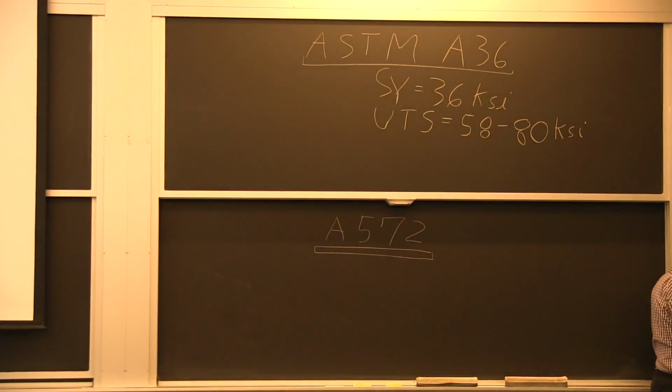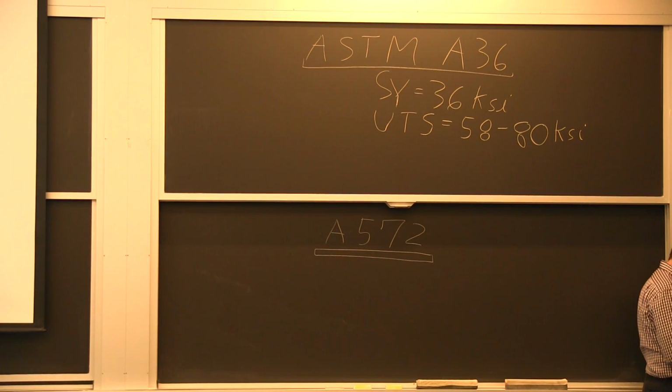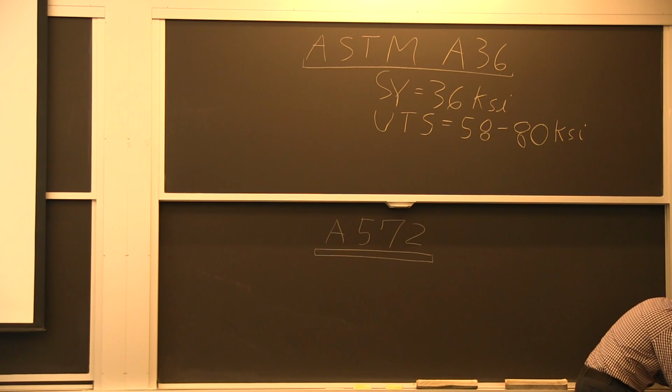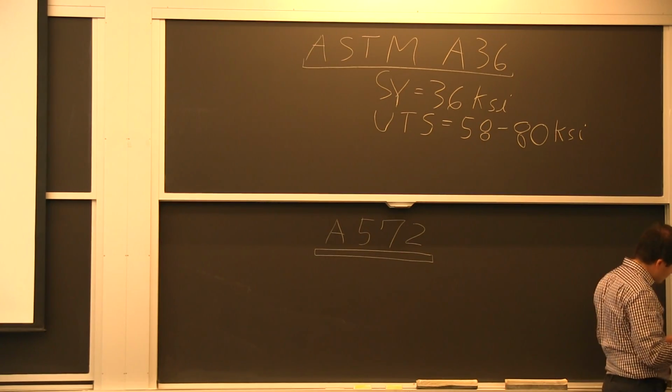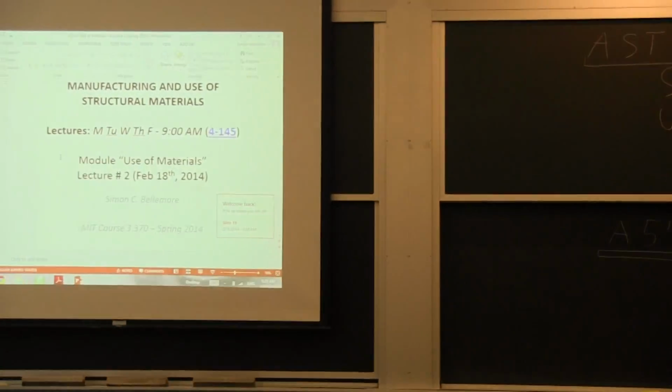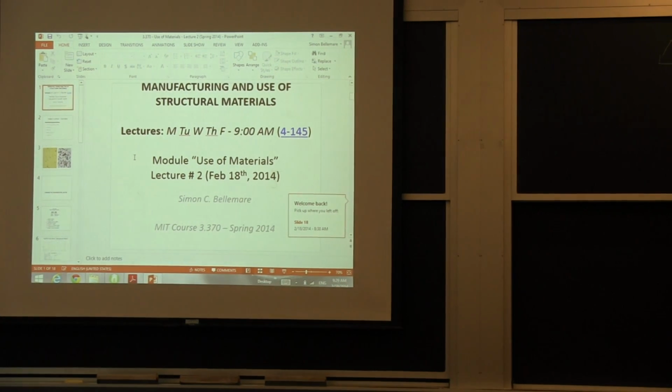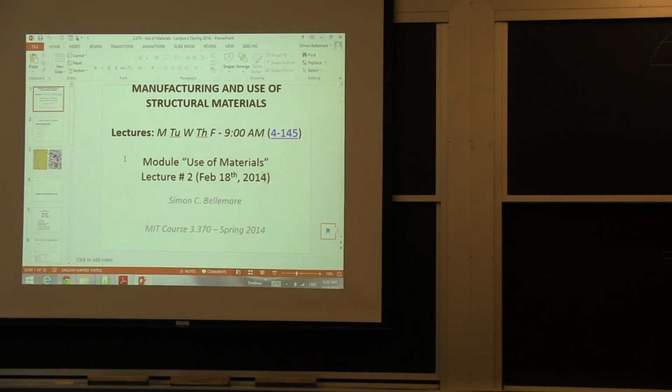You have different types of that same ASTM A572 alloy: type 1, type 2, type 3. As you go down the road, say we take a type 5. Type 5 tells us maximum 0.06% vanadium. It's very low.